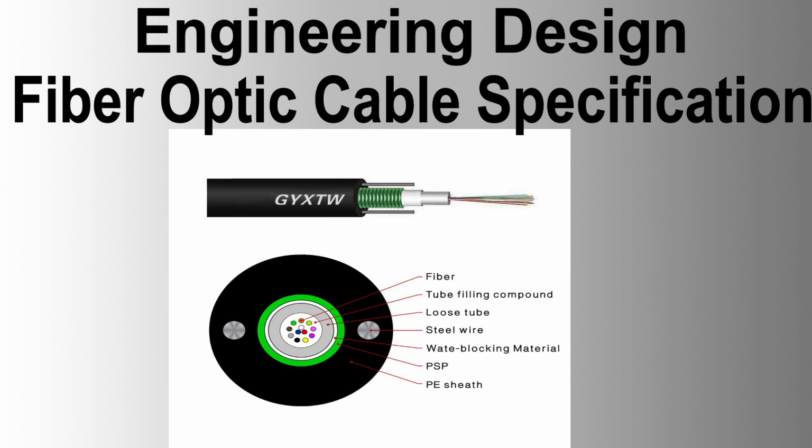Markers. Installation of markers. Cable route markers shall be installed upon completion of the cable installation and generally after the cable trench has been backfilled and compacted. Pipeline markers positioned along the route, including various crossings and direction changes, shall also include cable identification as approved.